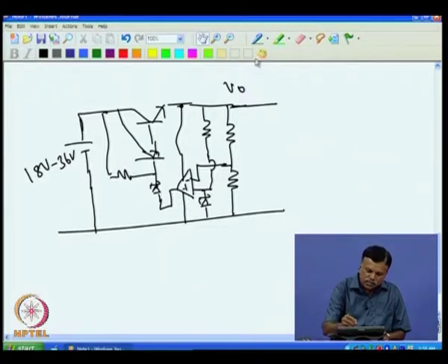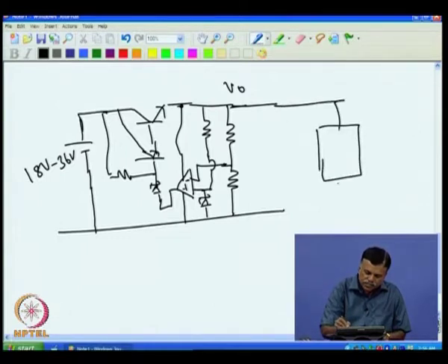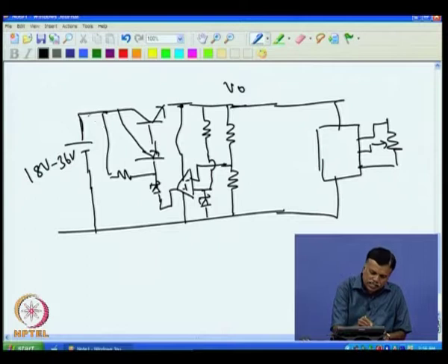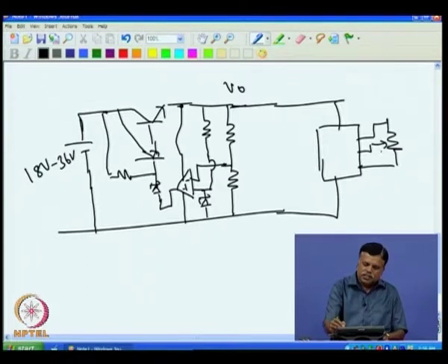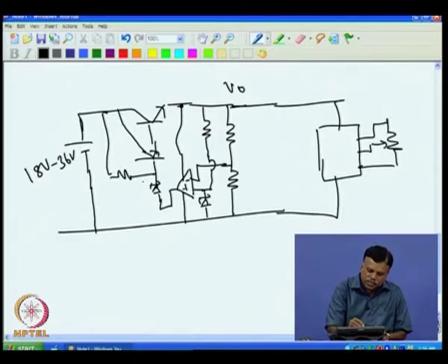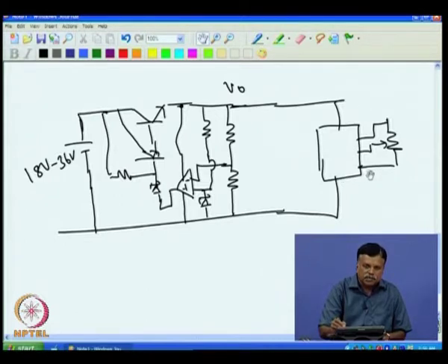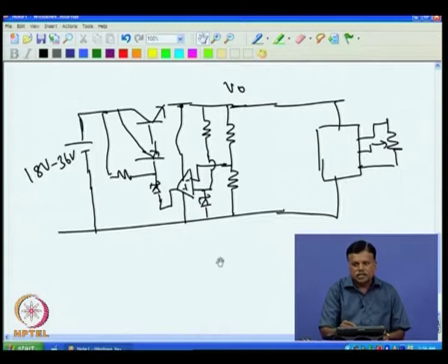In the actual case we will put a current transmitter here, that will be powered by this regulated voltage. Then we will have our potentiometer connected here. When the position varies, the current drawn by this varies, and so does the current that is coming from here. So, the total current that is going will be the current consumed by this and the current consumed by this plus the current driven due to this. So, we have first the voltage regulator part, then the current transmitter part. First let us concentrate on the voltage regulator part, then we come to the current transmitter part.